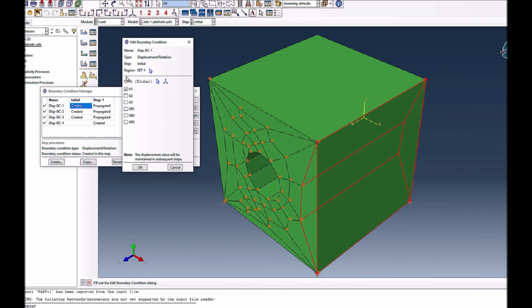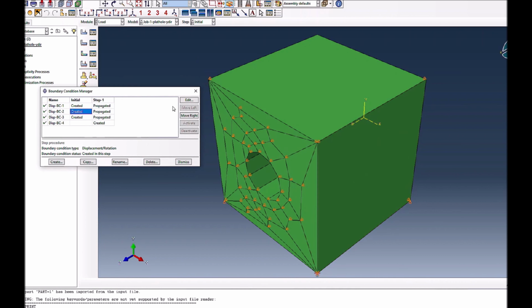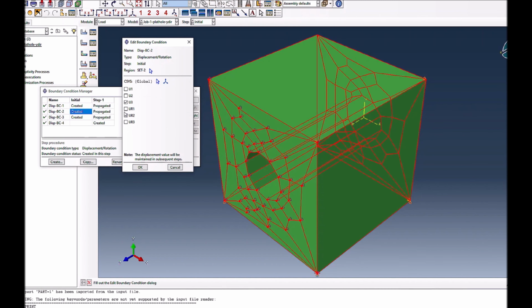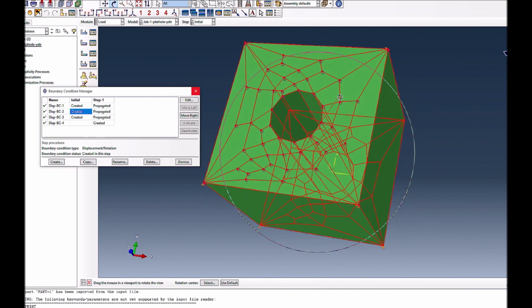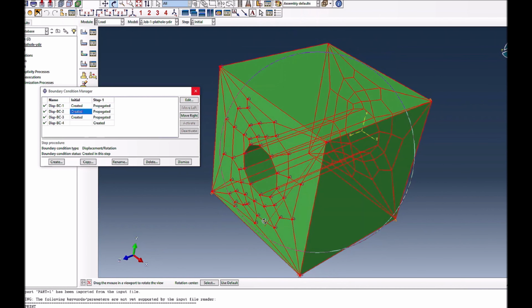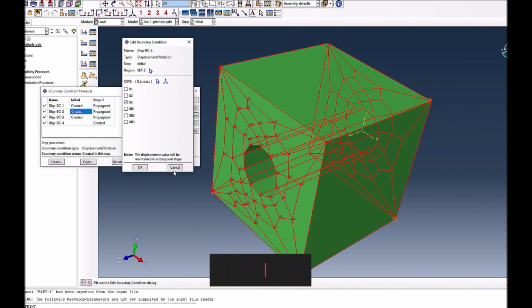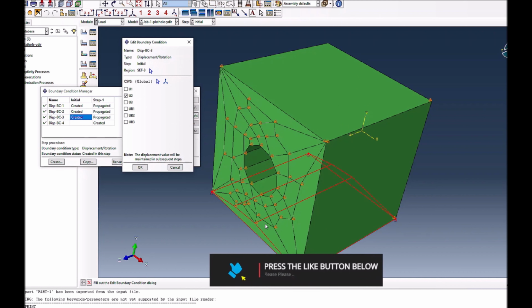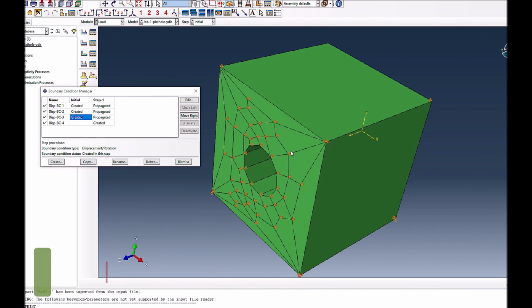You see this surface is fixed in one direction, which is X direction. This is fine. Then there should be another surface which should be fixed in 3 direction. So this is 3 direction, and I think it's this surface here. You see the Z direction is fixed, which is this direction here. And then there should be one with Y direction, and you see this is U2, and it's the bottom surface which is fixed in Y direction. So this is the correct condition for a uniaxial case.